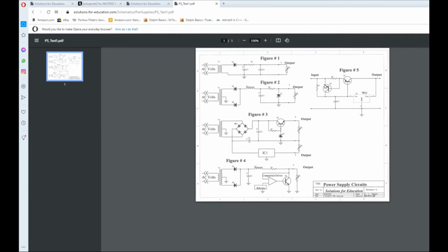So what is the purpose of this circuit right here? The whole purpose of this circuit is to prevent overcurrent. This resistor here is in there so that this guy kicks in and starts adding some power assist to this guy. So he's the one that's really controlling the regulation. So guess what you'll have? You'll have a really nice clean 12 volts come out here, and it's a positive 12 because this guy here is a 7812. So you see how this works in.